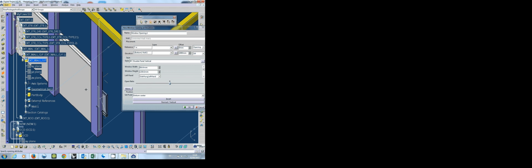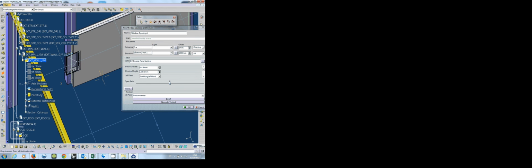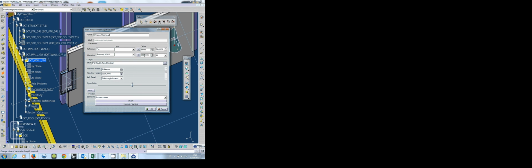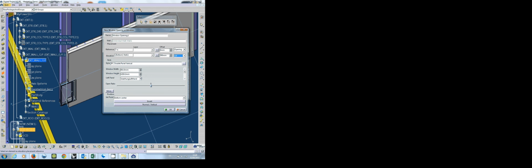Okay. So the reference elevation, this is the offset. I can make it a minus. Oh, sorry, this is the height. Oh, that's a sill. So sill is 1 meter height. I'll give it 300. And there's something wrong with the location, right?